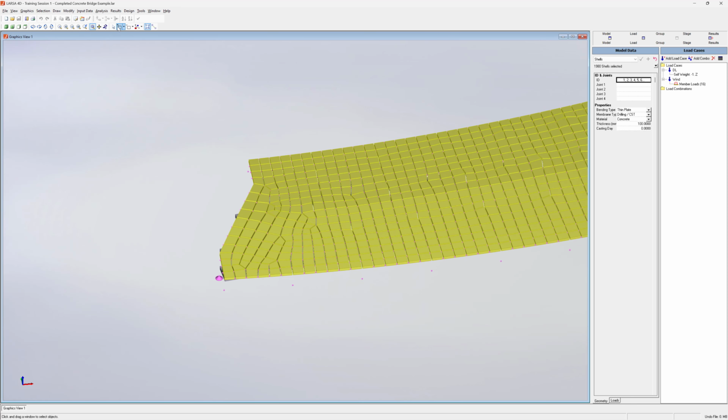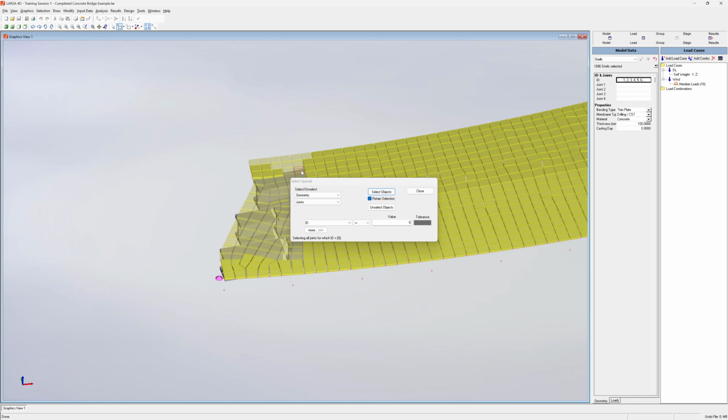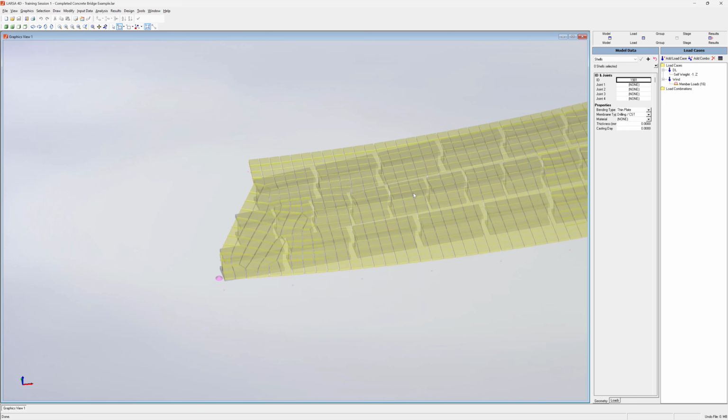The selection tools let you isolate parts of the model for editing or analysis. Select or unselect objects by clicking or dragging a selection box. Filter by element type, like joints, members, or tendons, for targeted selection. Use the option to hide unselected elements for a clearer workspace. The Select Special tool allows you to select or unselect based on filters such as group membership or element properties. You can also use keyboard shortcuts: S to select all, U to unselect all. Additional shortcuts are available in the menus and help documentation.